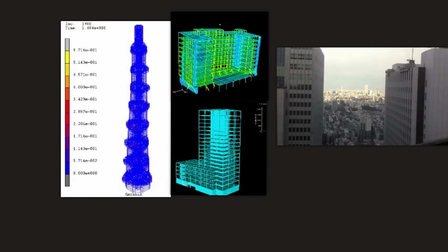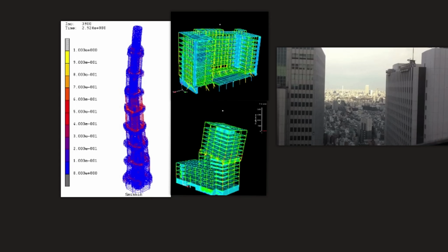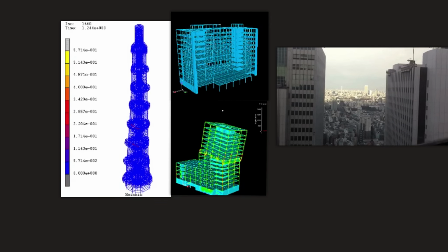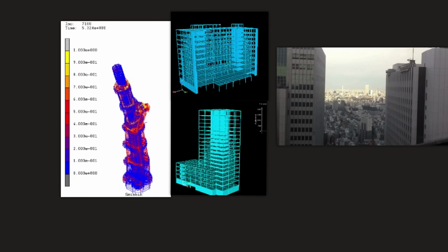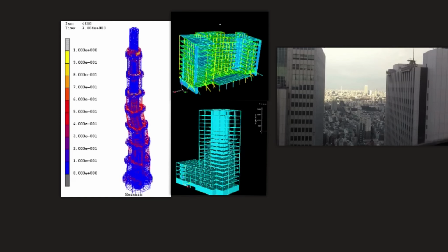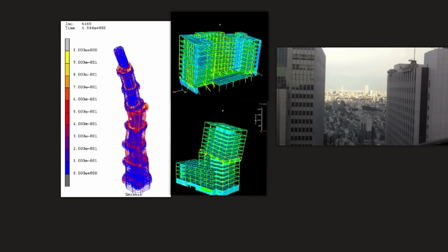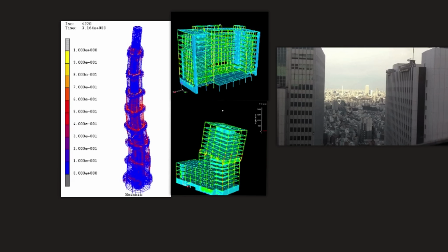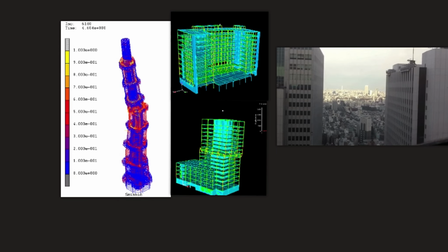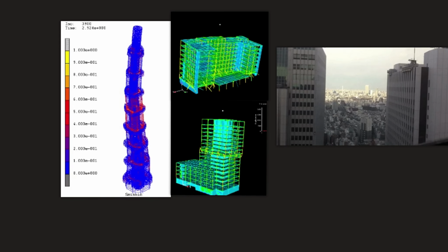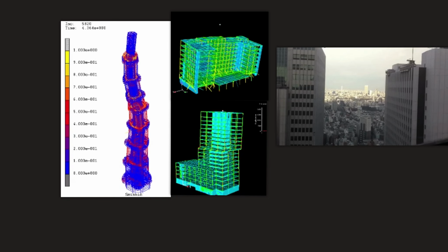Then definitely, as the building, you can see in this video, sways in the air, there is a certain amount of resistance offered by the surrounding air, especially given the fact that these structures are pretty long in size. So there is aerodynamic damping as well because of the surrounding fluid. Now on top of that, there may be vibration isolators, and vibration isolators may contain certain elastomeric materials. So there will be a certain dissipation of energy in those materials. So there are multiple mechanisms in which the energy gets dissipated.